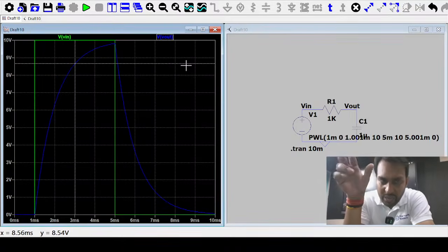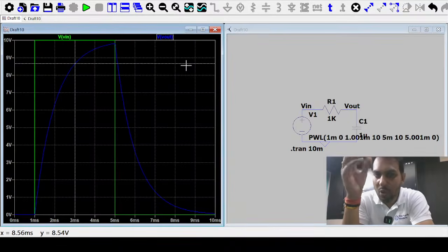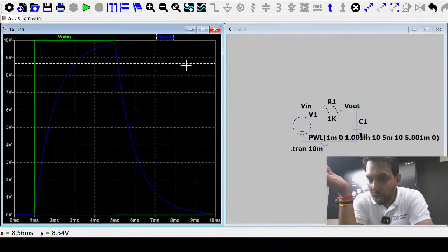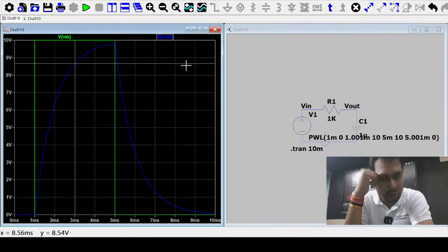It depends on the pulse width, and it also depends on the time constant. So you can change your R and C value and make your own idea. This is not as simple as you are thinking. You can improve that circuit, just like I designed one question. You have a pulse with a frequency f, and now I want 2f. So what can you do in a circuit so that it will perform 2f?